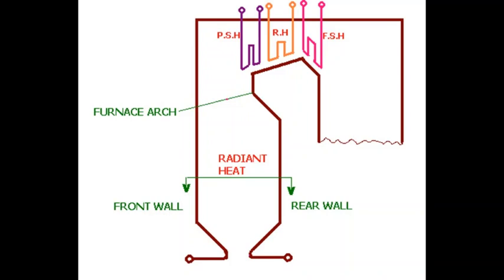In that case, we install another pump, which is called circulation pump. However, due to this circulation and continuous separation of steam, we continuously introduce water inside the drum and take out saturated dry steam out of the drum, and that is taken for superheating.